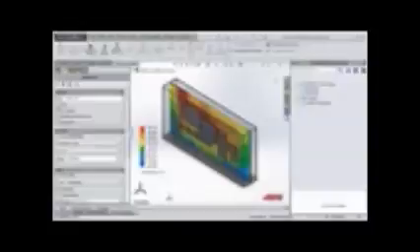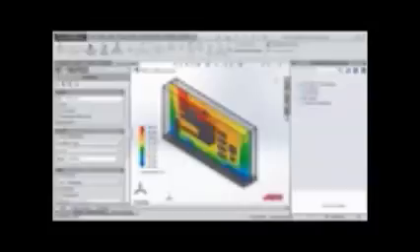I will now hide the surface plot, and under plane plots, double-click on the Z plane plot. Under General, click on Show to show the plane plot. We will unselect Mesh and click on Show Manipulator to activate it. Using the manipulator, you can drag the plane through the model.